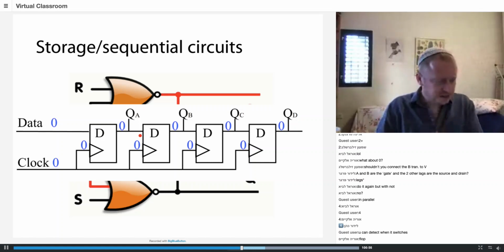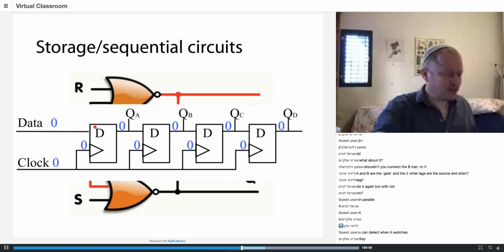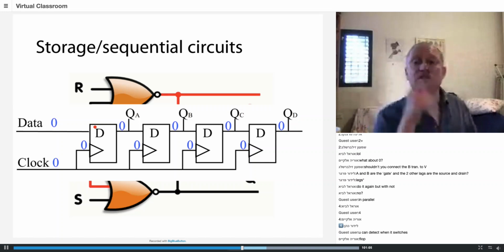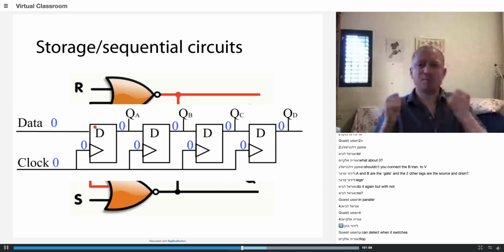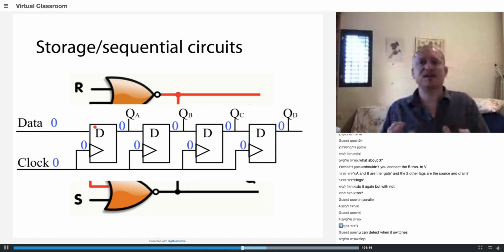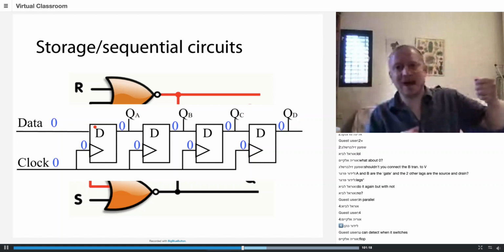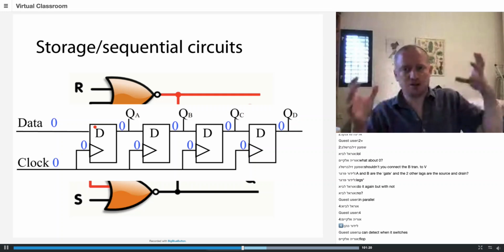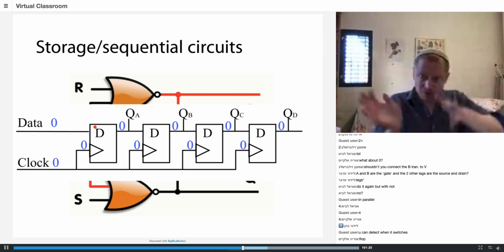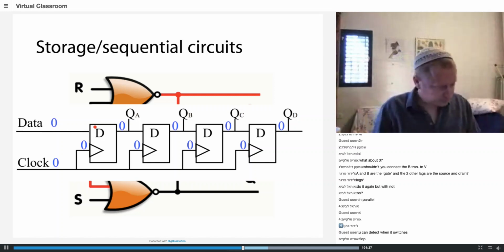Synchronous circuits are very helpful for the attacker. And why is that? Because all of the flip-flops switch at the same time. This is a very powerful signal. So it's easier for an attacker to detect this bang, this change that happens on the clock, because everything is synchronized. It's happening at the same time, even where the logic is scattered all around.